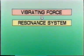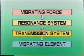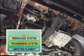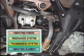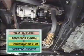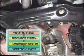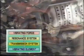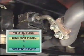Let's sort out the elements of the mechanism of this booming. In this case, the engine vibration is the vibrating force, and the exhaust pipe forms a resonance system. The exhaust pipe support forms a vibration transmission system.